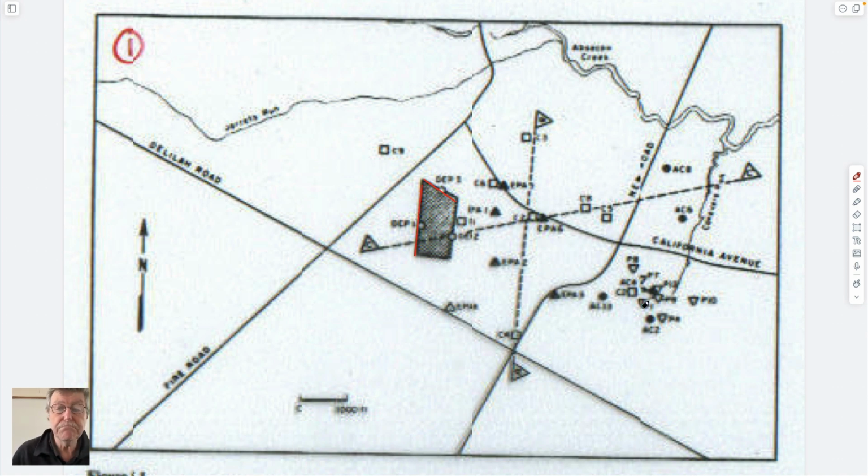So the idea is this. You pick up some components in this drinking water well. I guess you're staring at a field, looking north, south, east, and west. It's got to be coming from somewhere. You don't know necessarily that it's coming from this direction, and so you have to be able to rationalize exactly what you look at. So I suppose one thing to do would be to look at regional wells in the area, look at the elevations of water levels in those wells, and be able to discern from the gradients exactly which direction the stuff is coming from. Right?